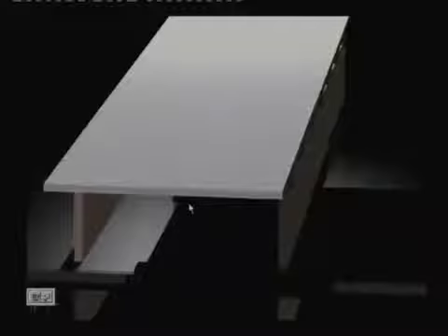So we cannot see the beam, but that is not the case. Our case is that we shall cast this beam as well as the slab integrally, so that we get a T section, and we can design it as a T beam.